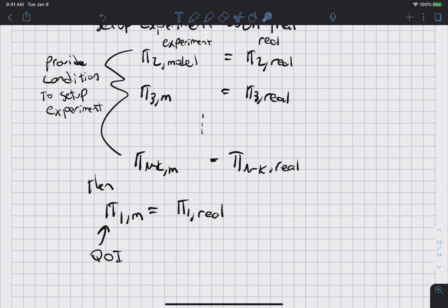Because the fluid going around the object, such as an aircraft or something like that, you may use a different fluid to test it in the experiment. For example, it's occasionally useful in studying drag on an object, say in a somewhat high-speed air, but not supersonic or anything like that, to test it in water, just because sometimes that's more practical, and sometimes for drag on an object in water, it's more practical to test that in a wind tunnel.